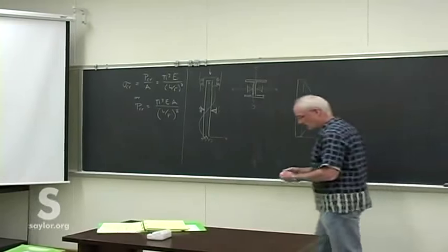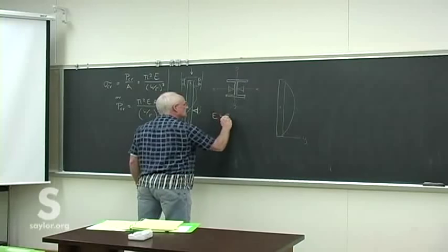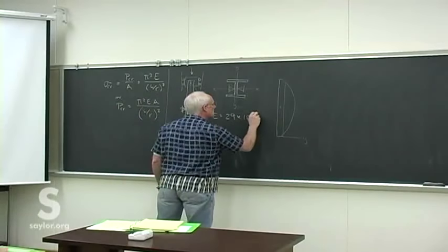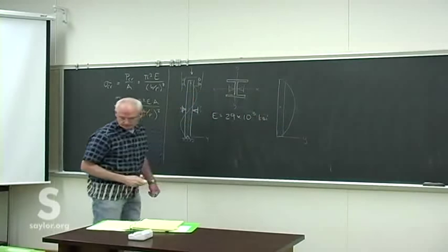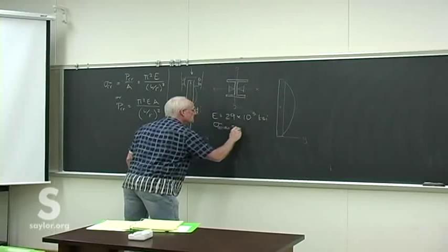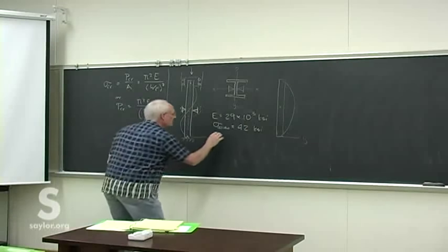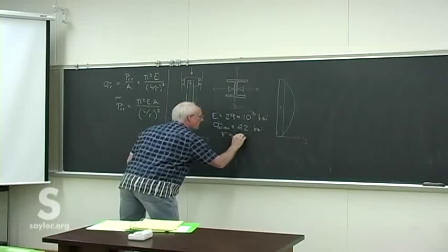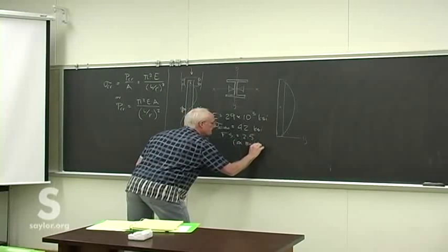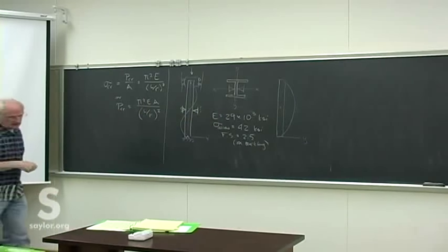So here's some of the other information you need for this. Steel beam, so we'll use 29 times 10 to the third KSI as Young's modulus. An allowable stress of 42 KSI. Factor of safety 2.5. On the buckling equation, not too big a deal.